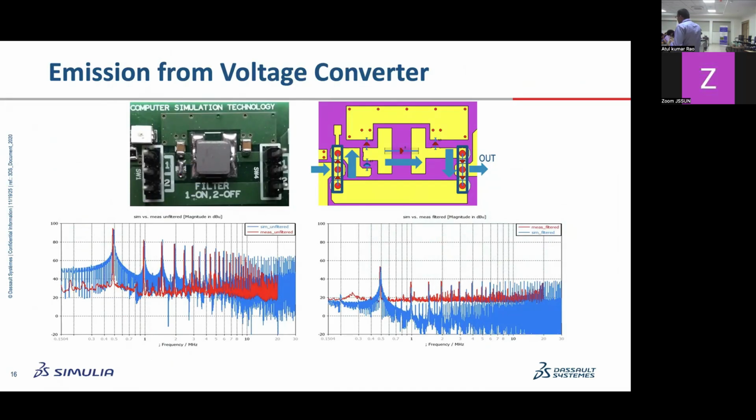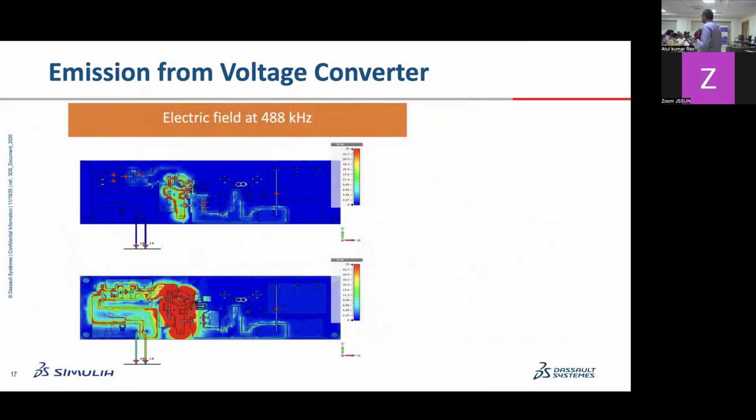The second part is where you have your EMI filter on, where you see that you do not want that high frequency spike that is coming in from here, and you can manage it. You can include that EMC filter in your design by talking to PCB experts, and then you'll see that the spike comes down. So the moral of the story is, even if you have a large amount of signal integrity that might be part of your design, if you do not pass EMI/EMC, that design is not released, so you will have to find a critical balance.